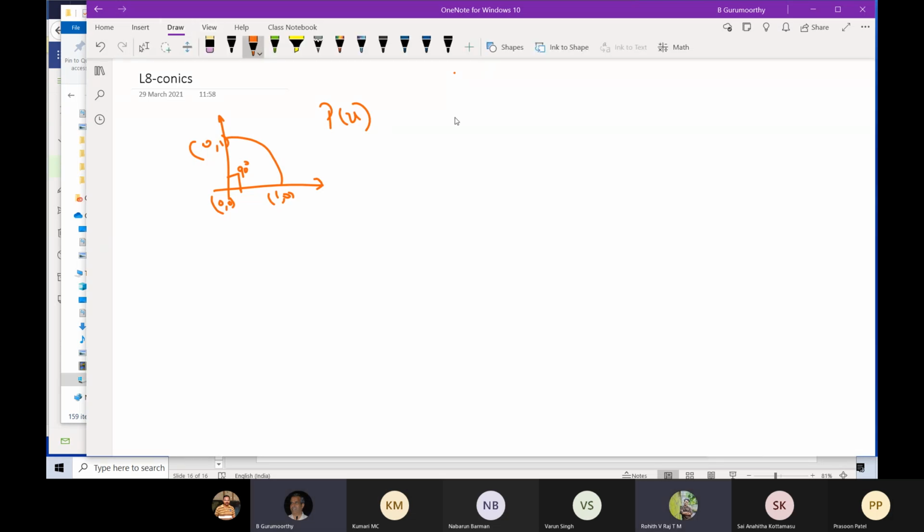The number of control points. Okay, so n. What do you think n should be? So 4. 3. Okay, so we have two choices. I'll put both here, 3 or 4, and we'll resolve this in a minute. What else do we need to specify? Remember, we had made this list of parameters for the spline curve. One chart was there. The next thing that we need to prescribe is K. So what should K be for a circle?